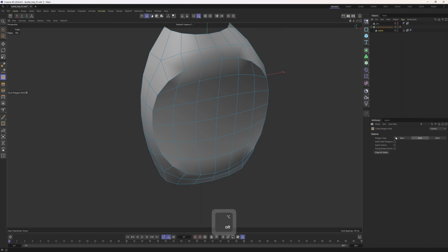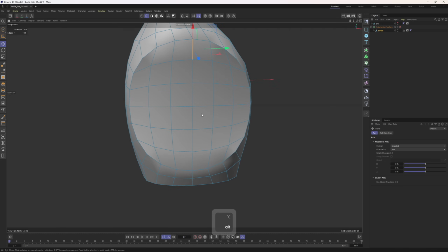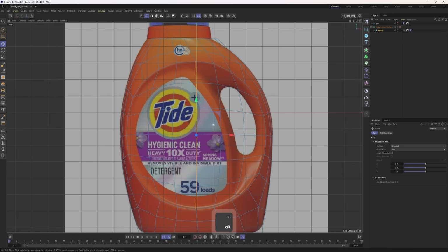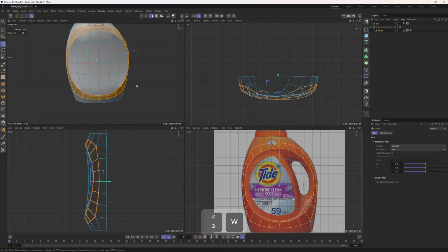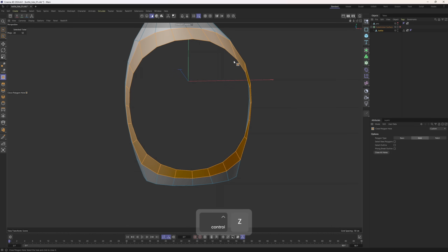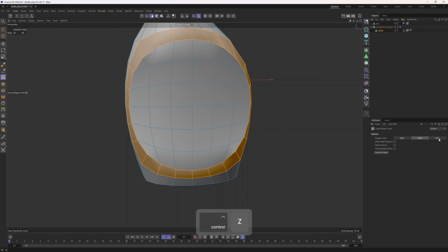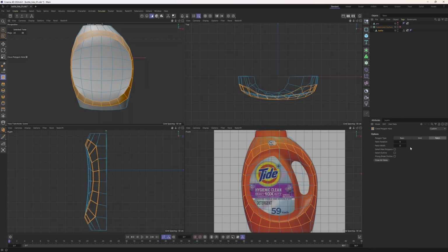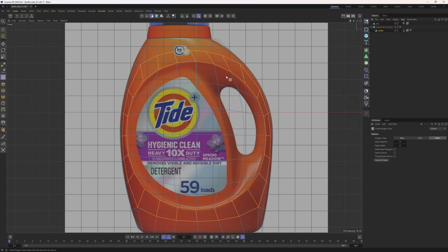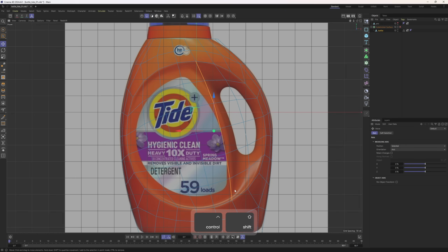Let's try the grid one, but this is going to give us this vertical structure, but we want to rotate it slightly. To do that, I will hit Ctrl Z, use this tool again, but this time I will select the patch mode. This mode will allow me to rotate this new geometry. So let's set this to -1. Now these edges are looking perfect for me.